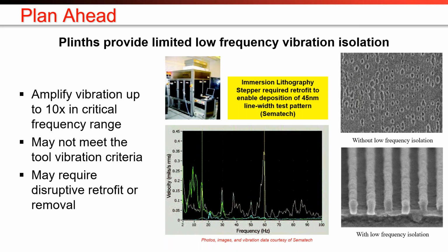It's pretty much gone by above 30 hertz. But at 5 to 15 hertz, you can see a tremendous amount of amplification, right? It's a mass spring damper. Its resonant frequency is clearly 10 hertz in the vertical direction there, and it's amplifying the problem. So the problem actually became worse, and the test pattern ended up looking like the image in the top right, which was worse with the rubber pads than without the rubber pads.